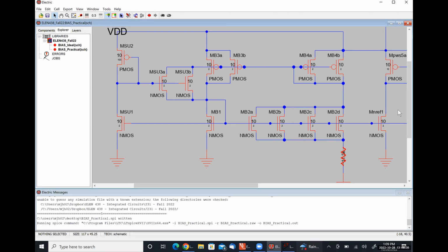So the resistor I have isn't quite the same as yours. My text is horizontal. Is there a different model resistor, or is that just the way yours worked out? Just rotate the text. I used a high-res poly 2 resistor, and I think it automatically does it.